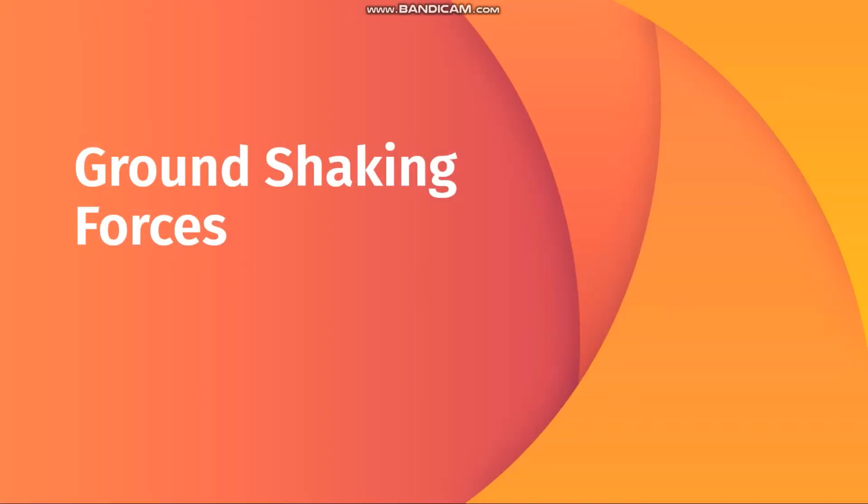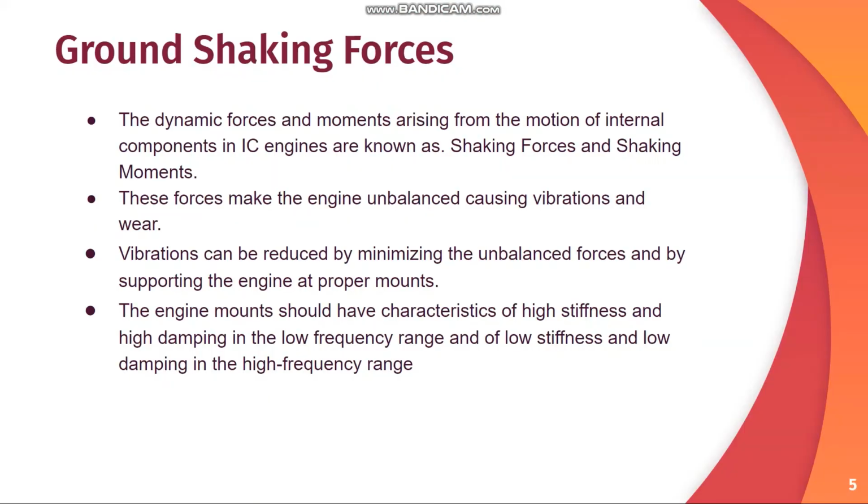Now, let us talk about the ground shaking forces. The IC engine is a machine whose components are always in motion. Thus, during various points in the cycle, it is possible that dynamic forces and moments may arise due to this movement. These forces and moments are known as shaking forces and shaking moments. These factors are responsible for the vibrations during the motion of the engine. These vibrations may lead to wearing of various engine components and the engine noise.